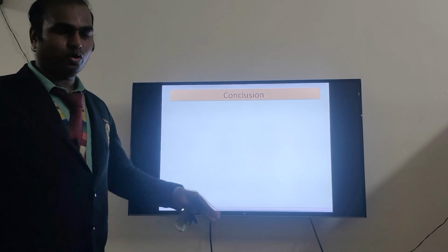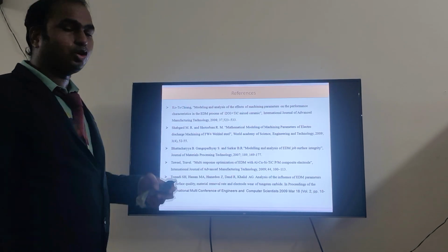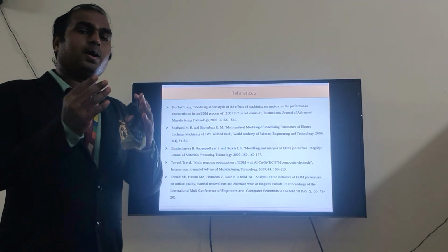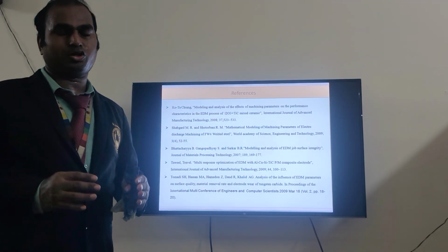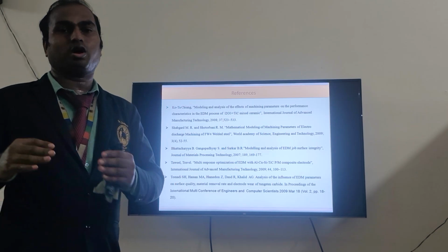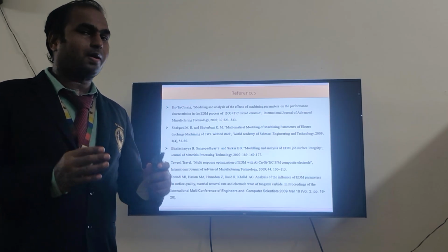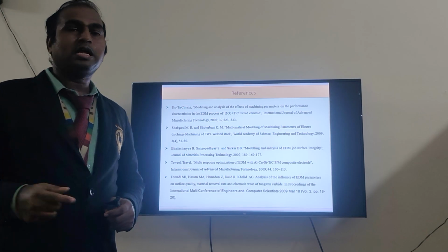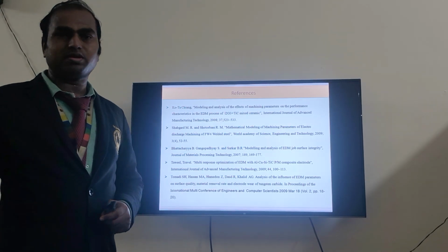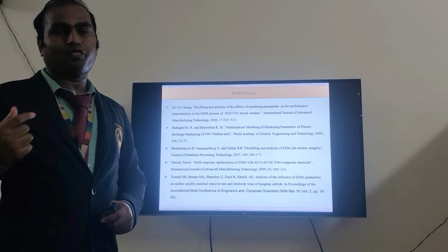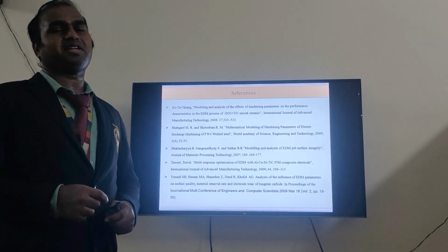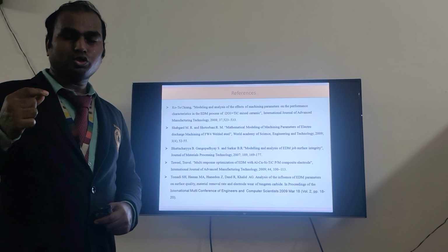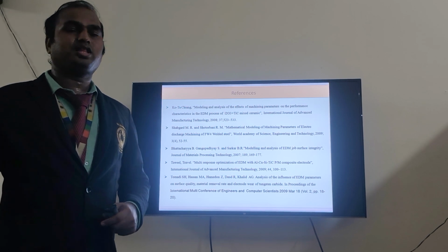I would like to conclude with the summary of the work done in this process. The special tool is an additively manufactured copper tool, made using a filament fabrication technique, compared with the normal conventional tool. The set of parameters after machining on the EDM X25 shows that the additive manufacturing copper tool performs better than the conventional tool.